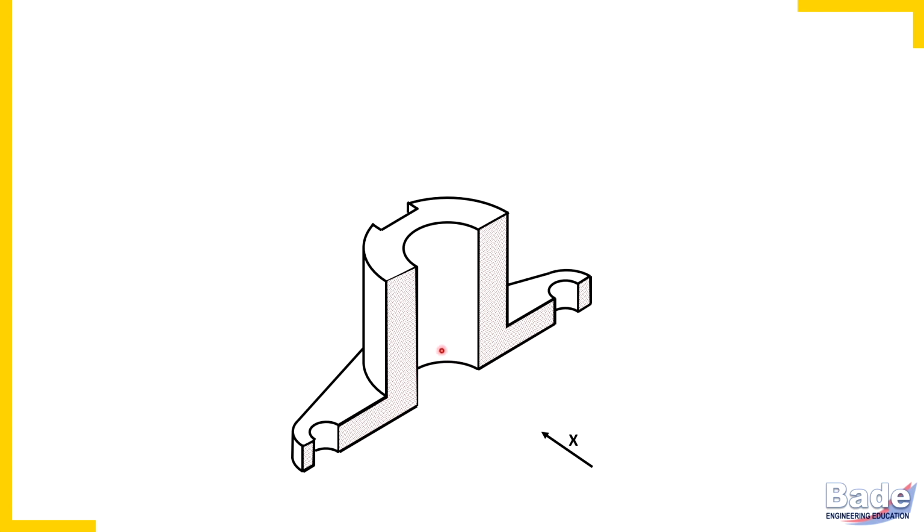But watch here, inside the hole, this semi-cylindrical surface is the original surface. It is not the surface that is created by the cutting. But this colored surface in the drawing now on your screen is a fresh surface that got created because of the cutting. Now try to understand one thing: the portion nearer to the observer is to be imagined removed.